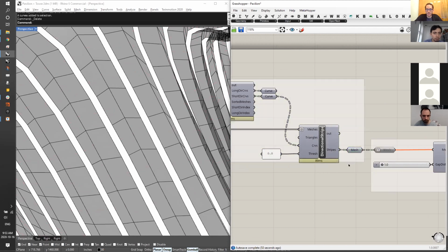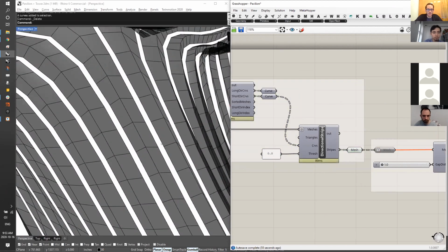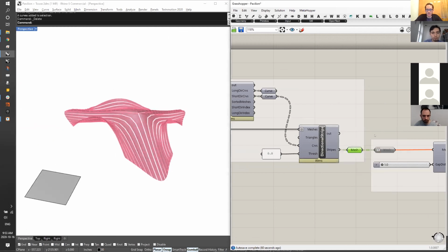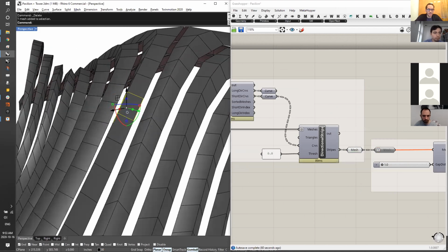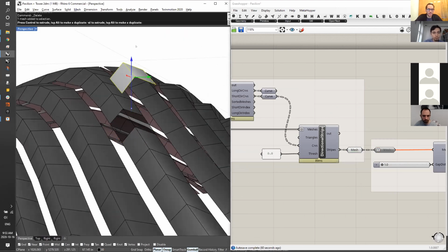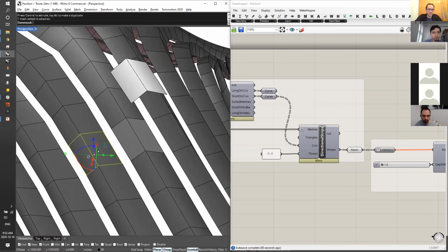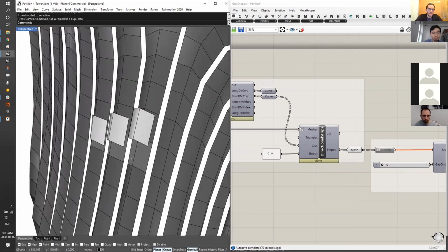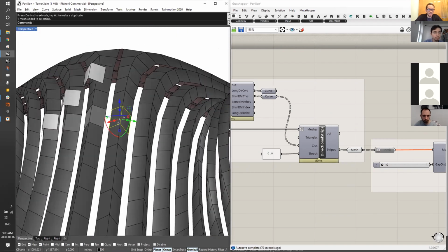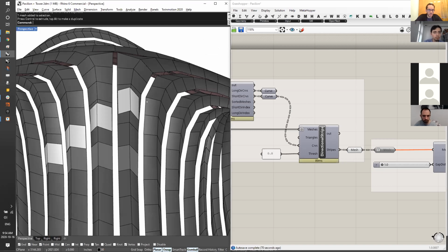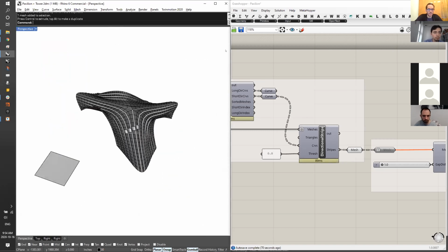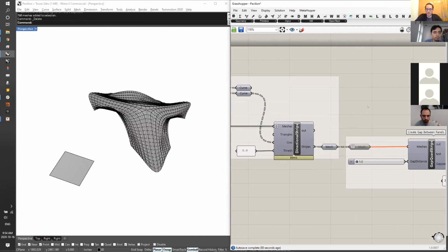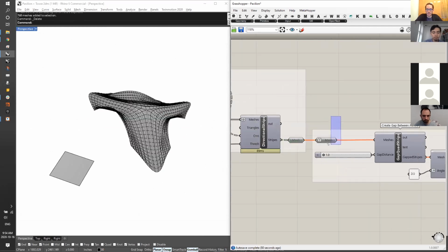If you want to build it just purely in Grasshopper, no Python, that's all it is. It's again looking at the meshes, looking at the topological conditions, and deriving a series of conditions from it. So in this case, we derive a series of, you can call these shingles, you can call these discretized bent panels or whatever, and then use that to start discretizing and panelizing the overall structure. So nothing new essentially, still replicating the same thing we built earlier.